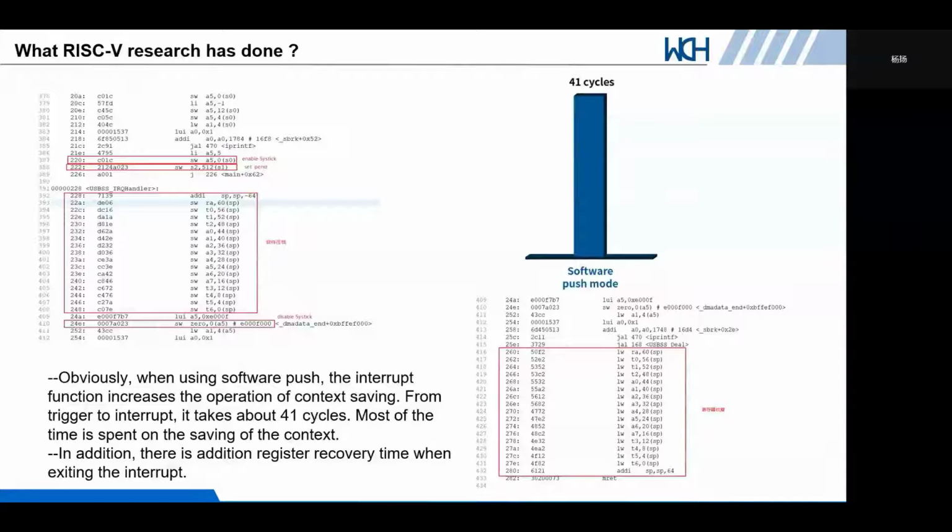As can be seen from the assembly code in the figure, first enable the interrupt, set the pending bit to trigger entry into the interrupt function, and use the tick to count. The initial count value is 0xFF, counting down. Set the pending bit to trigger the interrupt.